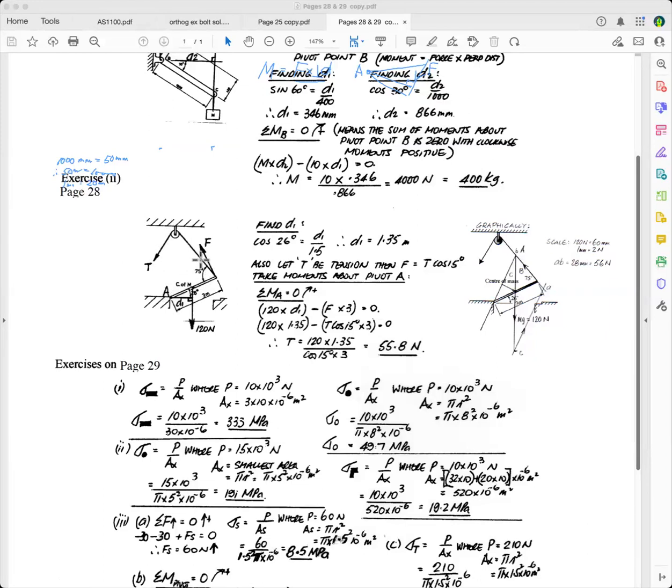You think you have to find the force here, and you're asked for the force there, and you're thinking, oh, is this force the same as that? But it is, because it's a cable. And so you've just got one force in the cable. So let's have a look at this. Weight forces always act through the center of mass. And so if I were you, I would put all the forces on the trapdoor to show the examiner that you know what's going on here.